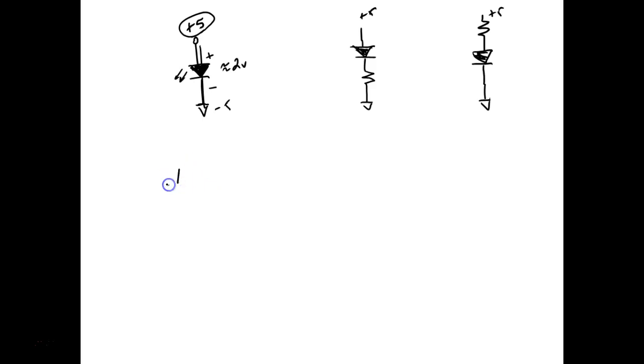So on this guy right here, this is a common cathode. I think they have them pointing, oh, I'm going to point them down, and I'm just going to do that. We know there are either 7 LEDs in there, or there might be 8 or 9, including the decimal points. And what they've done on this one is connect all the cathodes together.